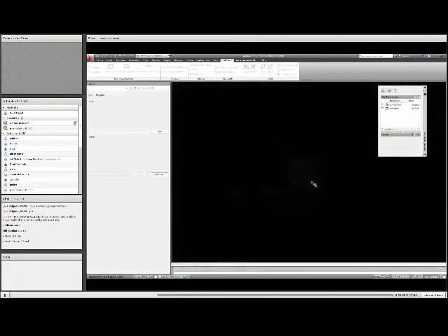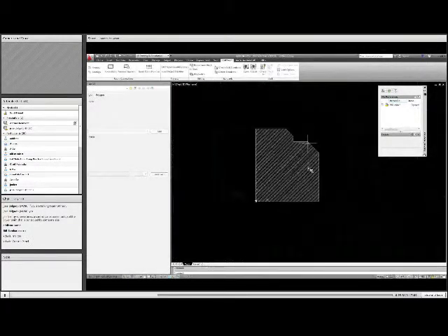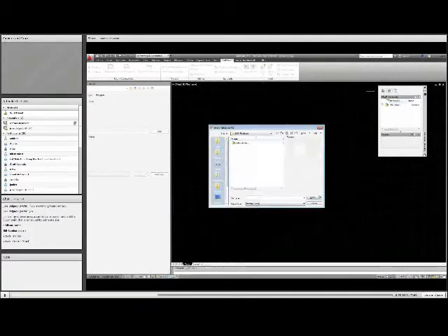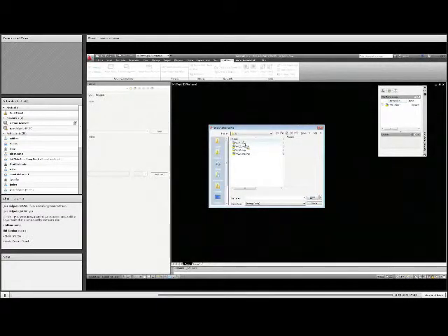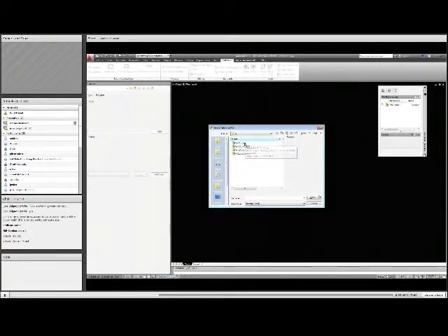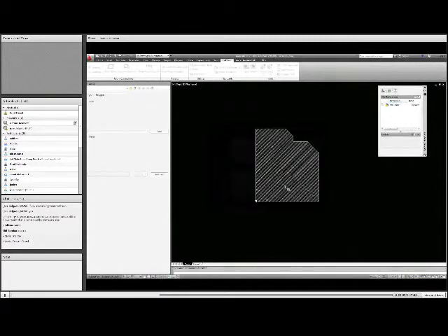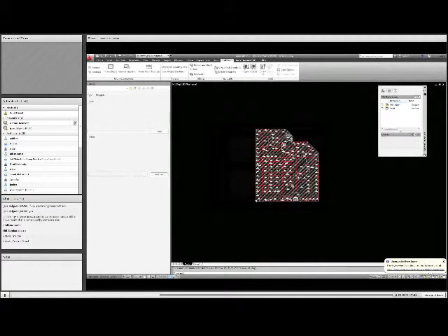So I'm going to grab ArcCatalog, and I have my 3 feature classes that I want, and I can just literally drag and drop those. And I want the rooms above, do some quick symbology, color, though I don't really have much data to do a thematic map on. And there is a perfectly georeferenced floor plan.